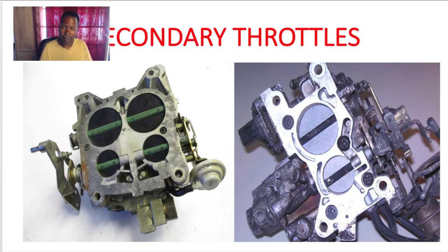And this one right here. If I punch it hard and try to pass a truck or racing somebody, you'll hear these two open up. That's a secondary valve for power. And in some cases, they have a metering riser in there also, inside some jets. When you punch on it and this opens up, you got 2 metering risers down there. When it opens up, it lifts the valves up out of the jets to let more fuel in.